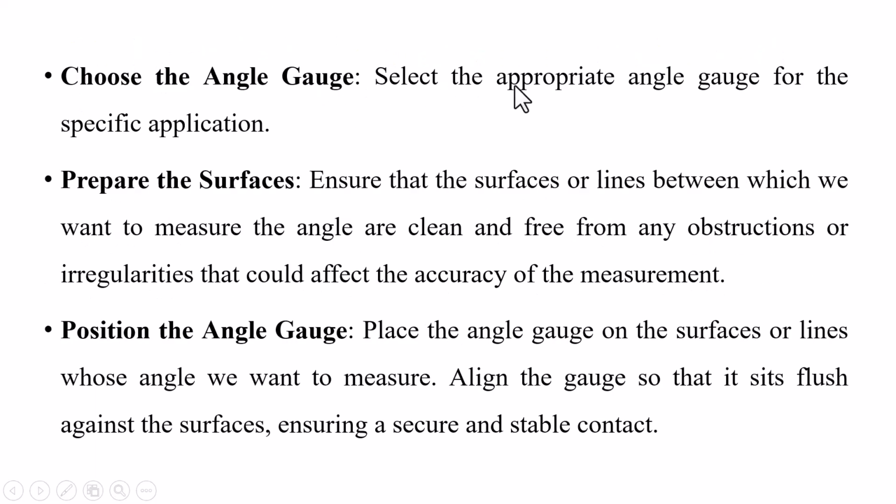Choose the angle gauge. Select the appropriate angle gauge for the specific application. Prepare the surfaces. Ensure that the surfaces or lines between which we want to measure the angle are clean and free from any obstructions or irregularities that could affect the accuracy of the measurement.